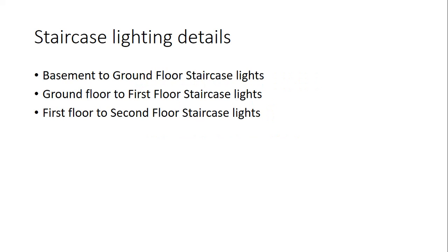So in this example, I'm assuming a 3-story plus basement building, and I have 3 different circuits for the staircase lighting: from the basement to the ground floor staircase, then from the ground floor to the first floor staircase, and from the first floor to the second floor staircase.